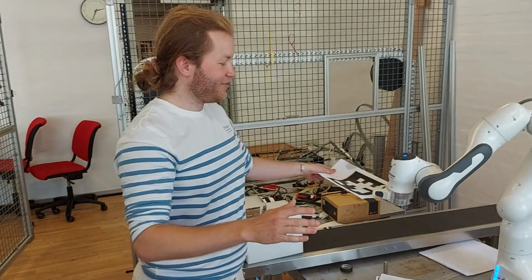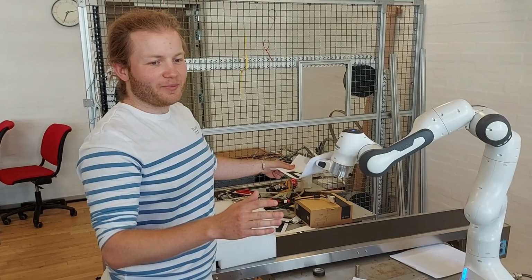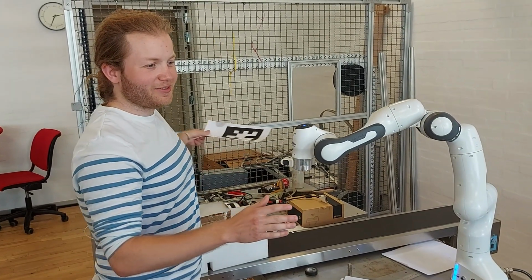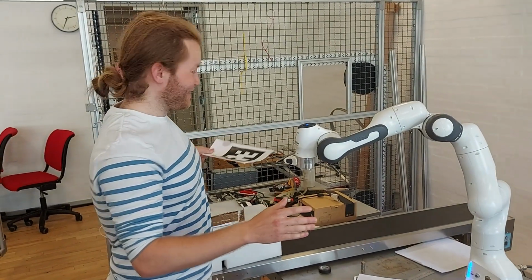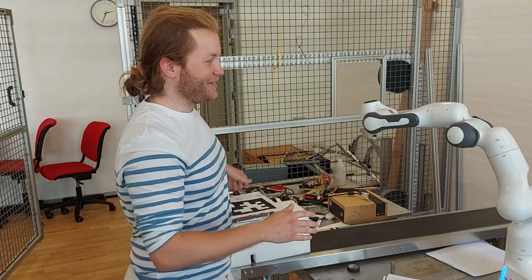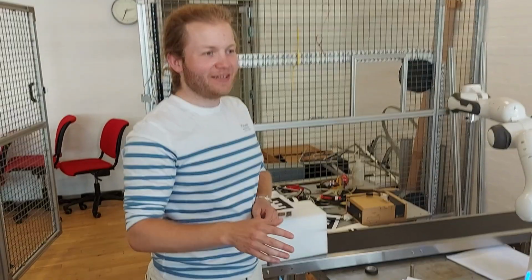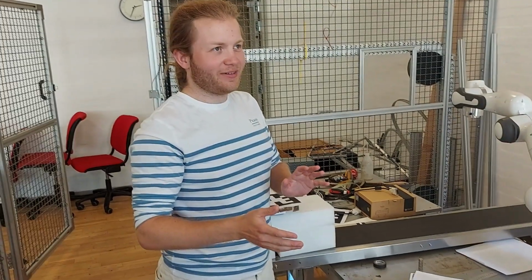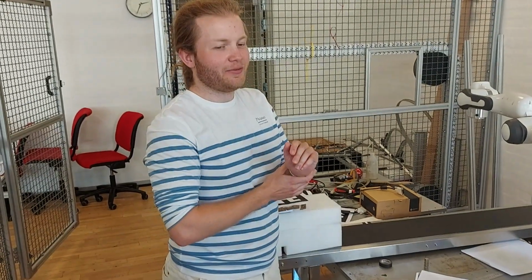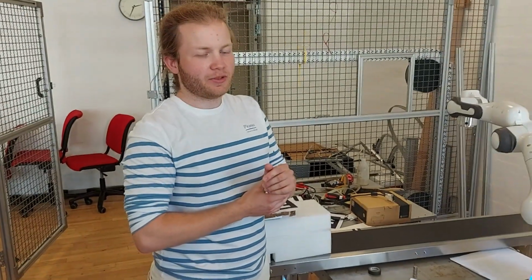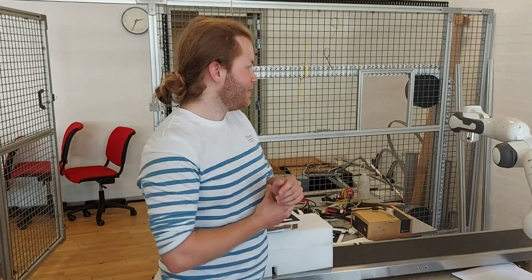and in the MRAC I low pass filter both the position reference and velocity reference because the MRAC was a pain to tune. But the AAC, it didn't require that I low pass filtered the references. It even got a little unstable when I tried.